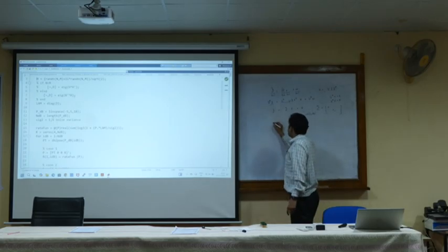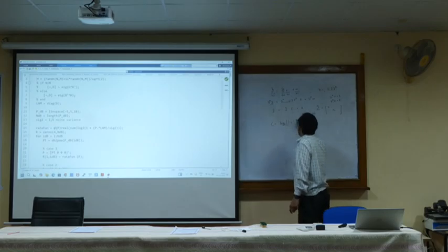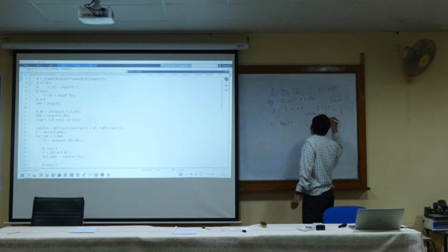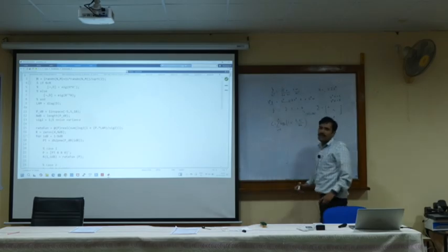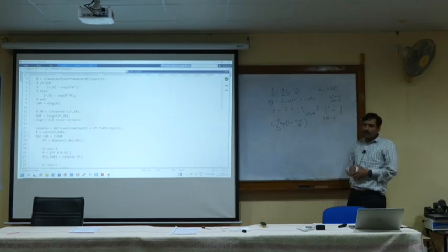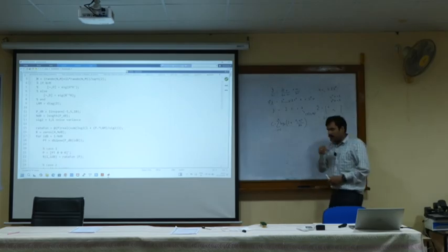So I can write the capacity C equals the summation over i equals 1 to the number of streams, here 4, of log 2 of (1 plus P_i sigma_i squared divided by N naught), where the expectation of |x bar i| squared equals P_i. This part is okay.